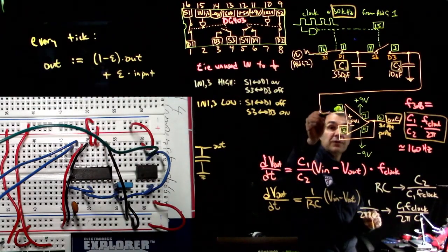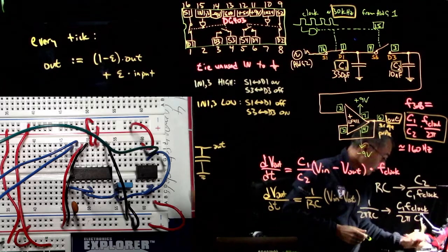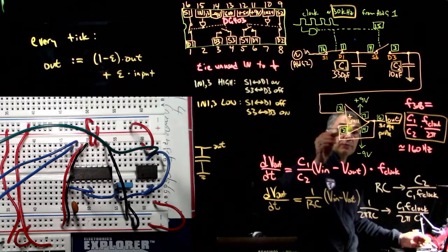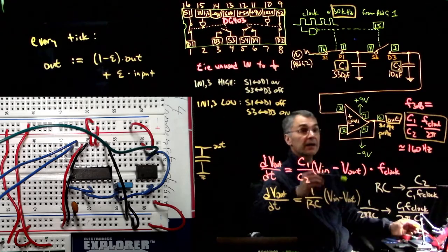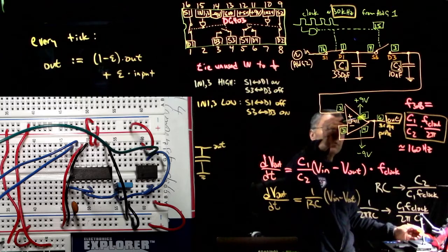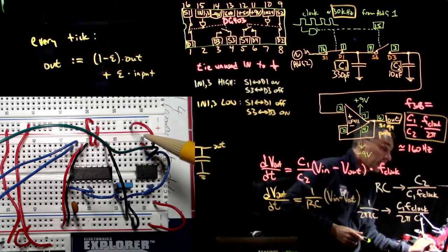So that was pin 3. Pin 2 is the inverting input. It just has feedback from pin 6. This blue wire goes from pin 6 back to pin 2 of the LF411 op amp. That's all except for power. Pin 7 is positive power, so here's pin 7 of the op amp going up to +9.